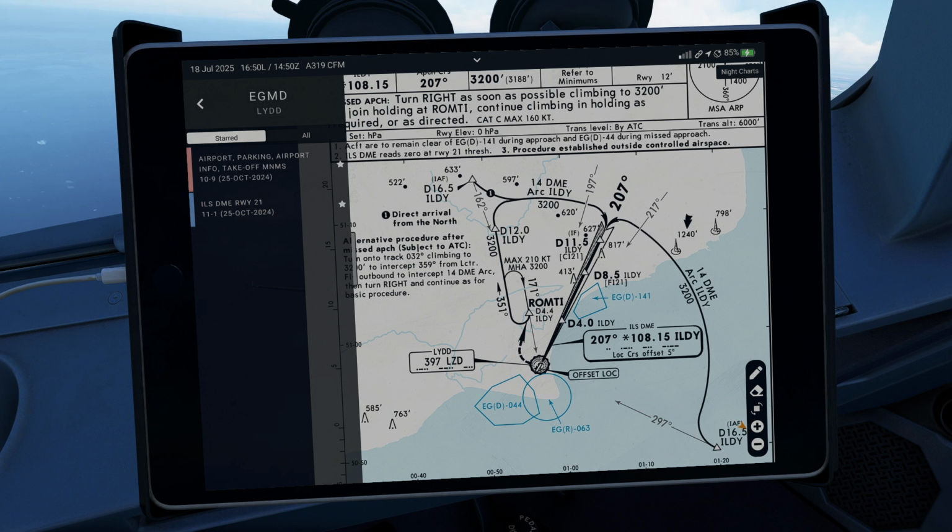But final thought: even if the offset exceeds 3 degrees, an ILS approach can still be published as precision if the local authority, for example the UK CAA, deems it safe, but with operational limitations and clear pilot caution.